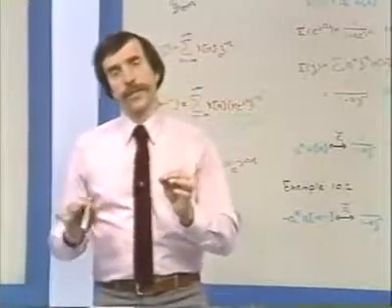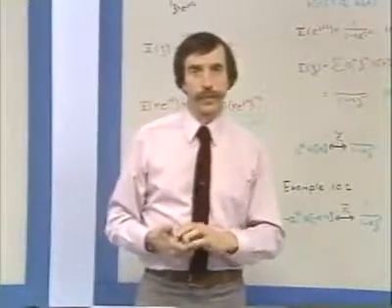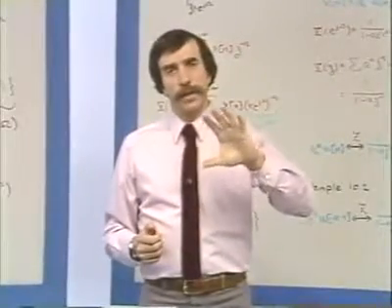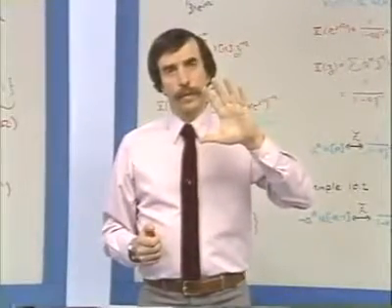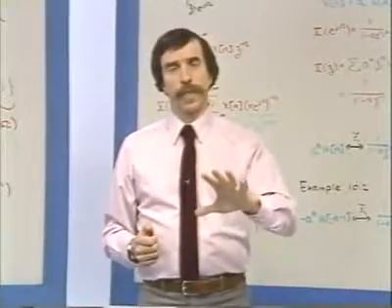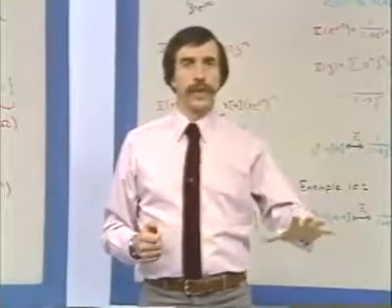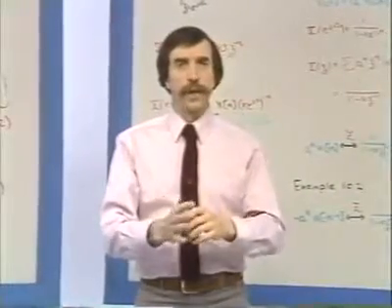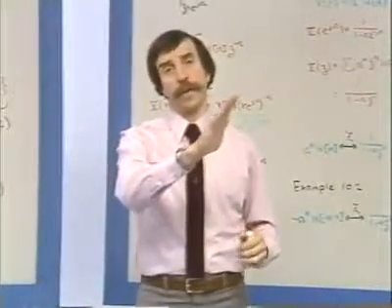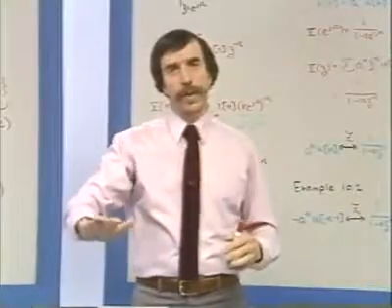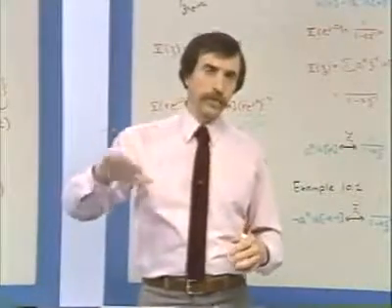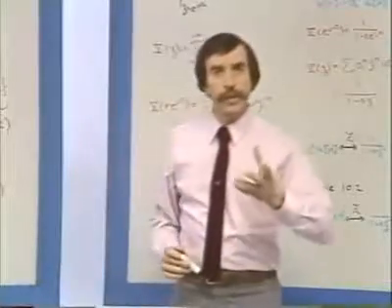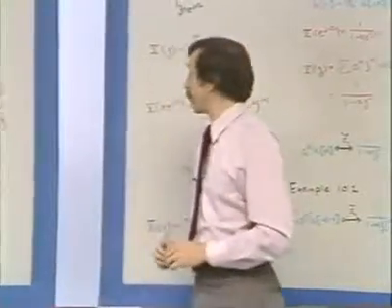Now, in the Laplace transform, we also had another important relationship and observation, which was the fact that the Laplace transform was the Fourier transform of x of t modified. And how was it modified? It was modified by multiplying by a decaying or growing exponential, depending on what the real part of s is. Well, we have a very similar situation with the z transform.